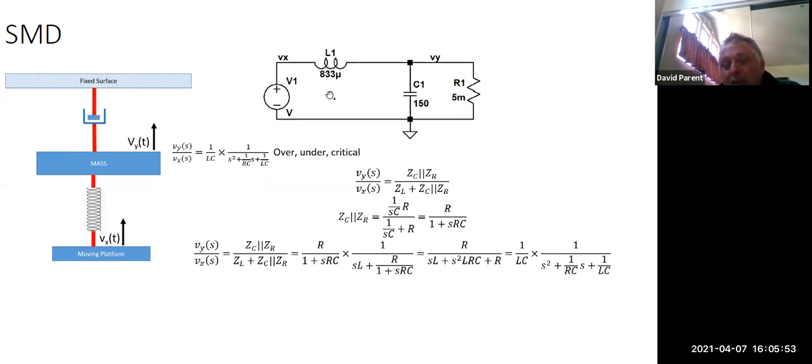And this will have a parallel denominator as well, right? If I short this, you can see that all these elements would be in parallel. Except now the voltage division is the capacitor in parallel with the resistor. And in fact, if you work it all out, you get the low pass equivalent.